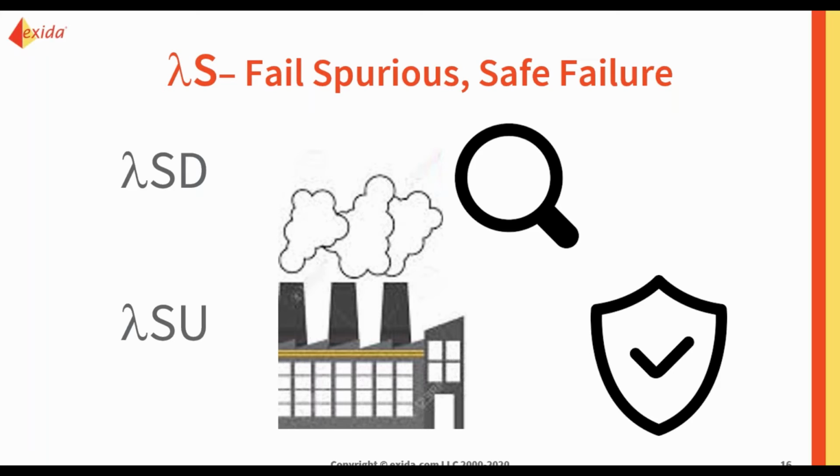And if you could move some of those, maybe add diagnostics, some of those undetected shutdown spurious trips to detected, or even lower your spurious trip rate altogether, that would be less frustrations, maybe less shutdowns, less time down, save you some money, hopefully.